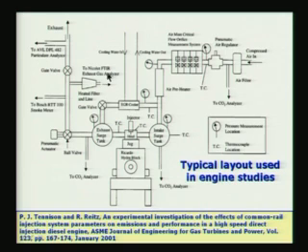Then we have an exhaust gas analyzer, as you can see here. This is the Nicolet FTIR. We have not discussed an FTIR instrument in our earlier discussion. It is a Fourier transform infrared spectrometer. The spectrometer will give you a spectrum corresponding to the species present, and by looking at the magnitude of the signals due to each one of the gases, we can find out the concentrations. So you have a gas concentration measuring device here.